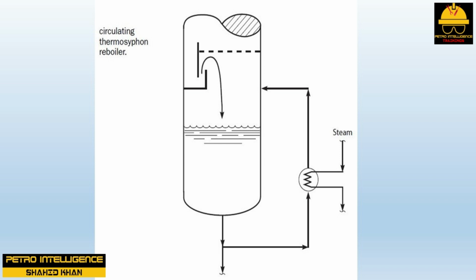is proportional to the height of the liquid level in the bottom of the tower above the reboiler inlet nozzle, whereas with a once-through thermosiphon reboiler, as described previously, the corresponding height is the elevation of the floor of the draw-off pan sump above the reboiler inlet nozzle.